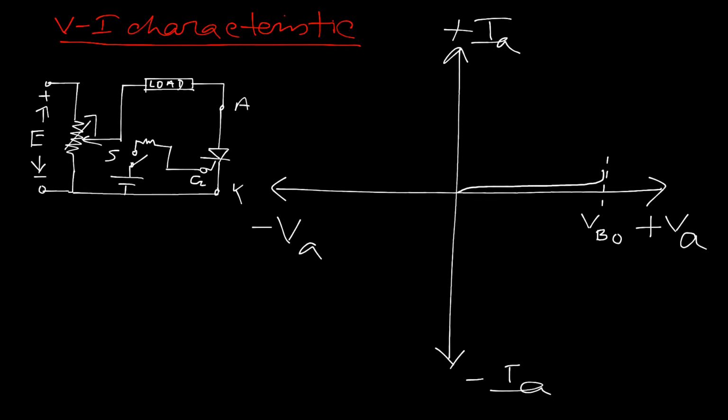As everyone knows, when the switch is off, the voltage appears across the switch. When the switch is on, no voltage appears across the switch, and the current starts conducting. A similar thing can happen for this semiconductor switch. So up to the point B, VBO, there is no question of the on state. That is why from 0 to VBO voltage it is called the blocking state or forward blocking mode.